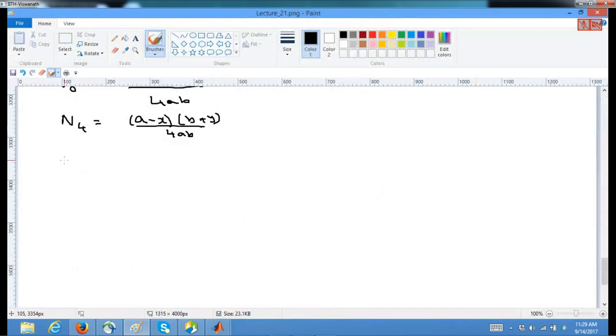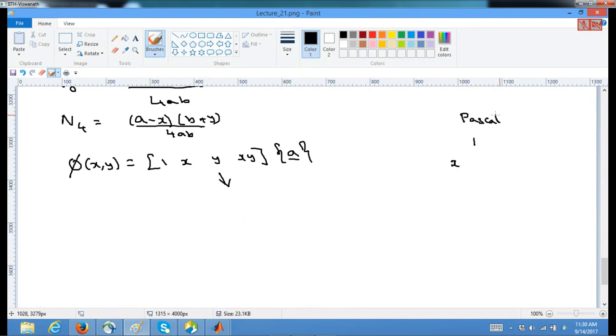When we are obtaining the shape functions, the important crucial part for selecting the approximation P is the basis. Why did I choose this basis? For that, let me recall what I have already said. You try to invoke Pascal's triangle.